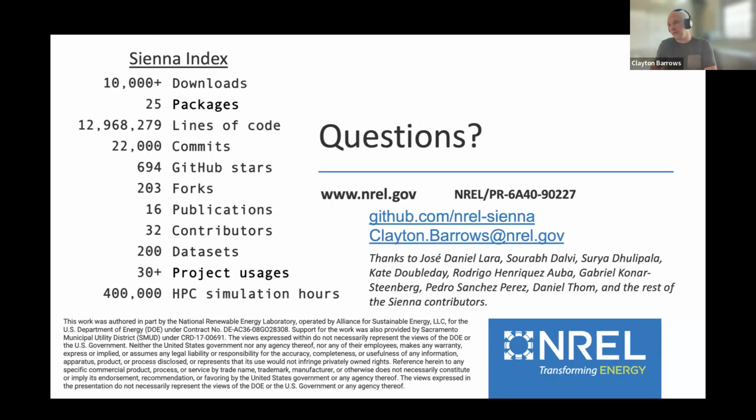There are still several areas that can be improved. Some of them are things like translating scheduling results that are obtained with linear approximation of power flow, so DC power flow assumption, translating those into an AC feasible power flow result, and getting both real and reactive power injection for a particular set point. Things like that are areas where there's additional need to refine the modeling capabilities, and we're actively developing many of them, and are finding that the Sienna framework makes that development fairly easy to plug into the framework where we can manage these large scale data sets and things like that. So thanks. That's a fun question that I like to talk about.